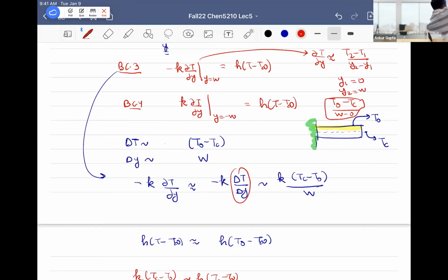So that is another way you can think about it. Another way to think about this is also your flux. The heat is transferring in the positive y direction, and it is cooling here. Then I want this value to be positive, and it is positive because the temperature of the center is higher than the temperature of the wall. So you can go about it either way, and it should all come out the same. Any other questions? All right.